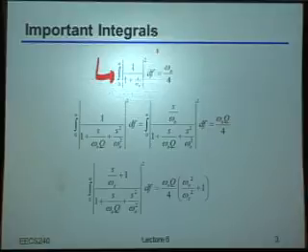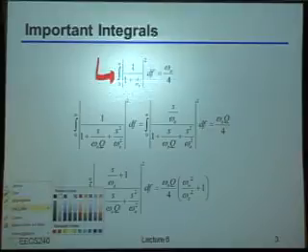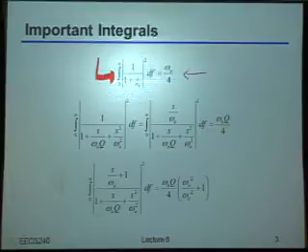And one thing to notice that's interesting here is that in this particular case, the effective delta f is basically equal to the cutoff frequency of the filter times pi over 2.